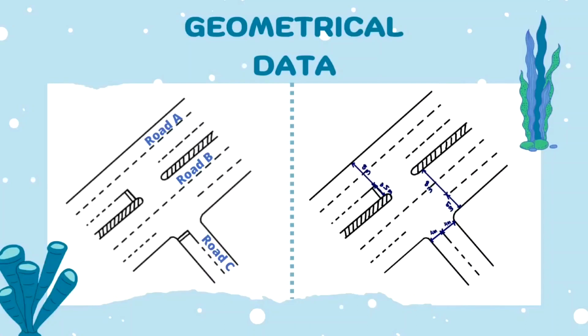For our project, this T-junction has three routes, which are route A, route B, and route C. Therefore, there are three directions from which vehicles come. According to the site observation, there is one lane in direction C, and there are two lanes for the straight movement and one lane for giving way to the left movement in directions A and B.